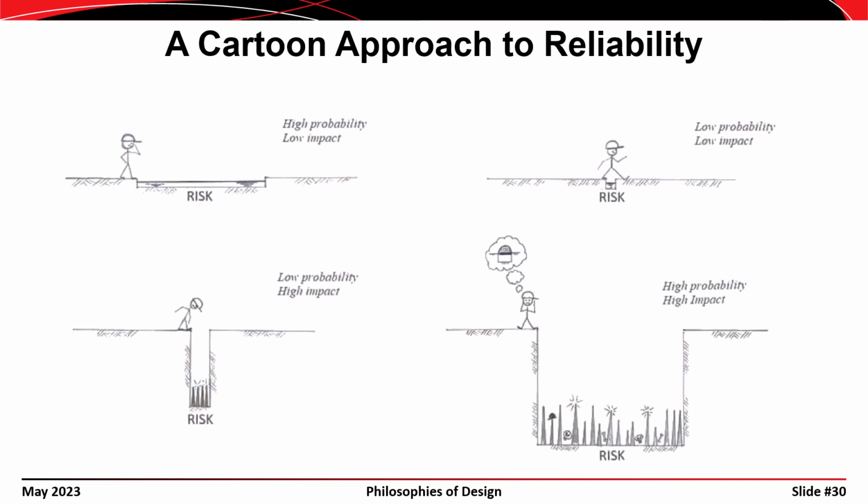The two images on top might represent serviceability limits, such as beam deflections and lateral drift limits for the structure. In general, the consequences of exceeding these limits are usually not severe, so as a result, we often check beam deflections under service live loads, load factors equal to 1, and we check lateral drift under reduced wind loads with a mean recurrence interval of around 10 years.